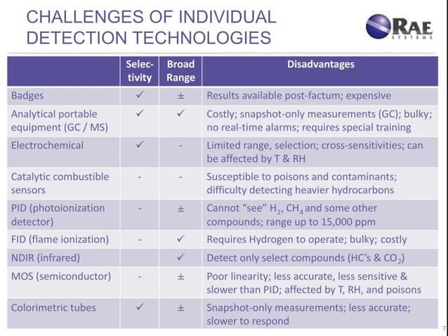Now, electrochemical sensors are also prone to cross-sensitivities, meaning that gases other than the target gas for a particular electrochemical sensor can cause the sensor to produce a reading. Or, even worse, cross-sensitive gases to which the sensor is negatively cross-sensitive can actually cause the sensor to underreport the readings for the target gas, which is a big safety concern. Electrochemical sensors can also be affected by temperature and humidity.